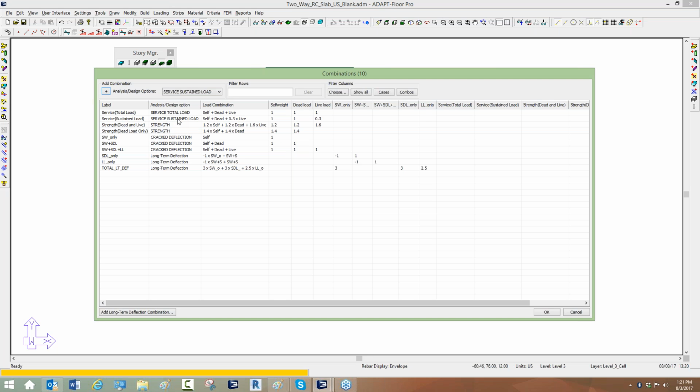For a post-tension slab, that's not necessarily true because you have different stress levels for both combinations because we have less live load in one of them, and some of the quote-unquote service or minimum rebar for PT is dependent on the stress level. But in terms of the RC condition, for ACI rather, I'm not an expert on all other design codes, but for ACI, we would get identical minimum rebar or service rebar from these two load combinations.